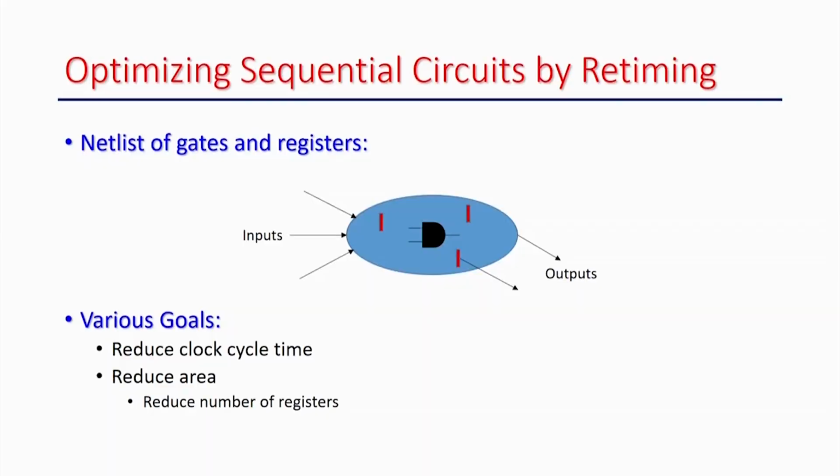Specifically, we are going to show how to formulate the retiming problem and how to solve it algorithmically. So both aspects we are going to discuss today. As you have seen, a circuit consists of several registers and combinational units like gates, multiplexers, demultiplexers, and all those things, right.